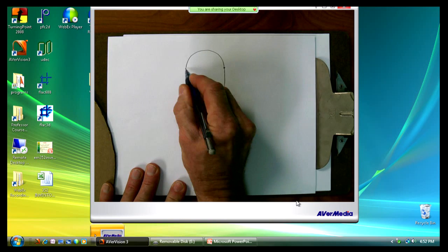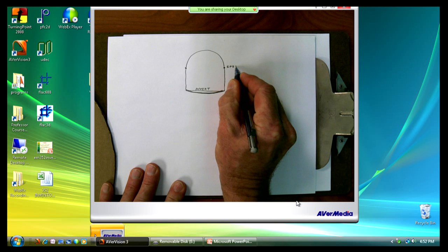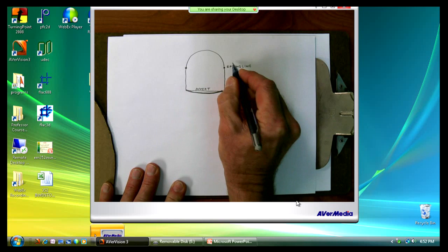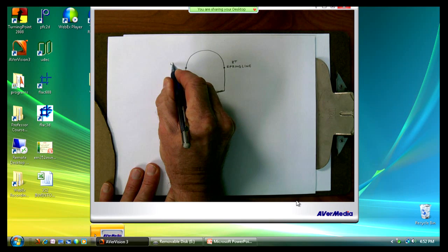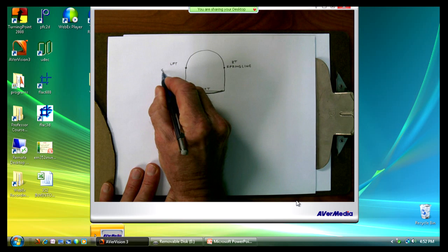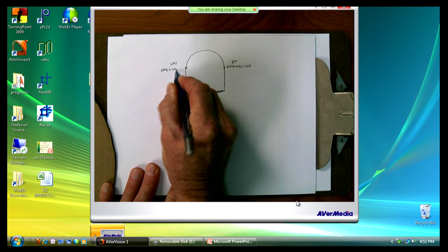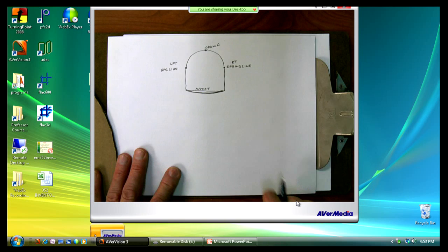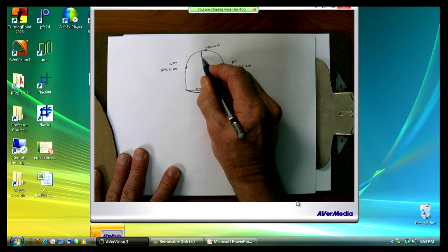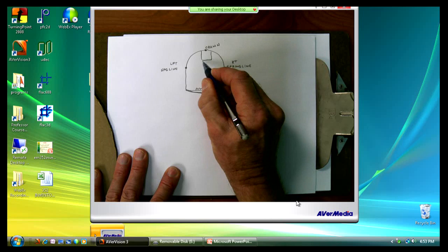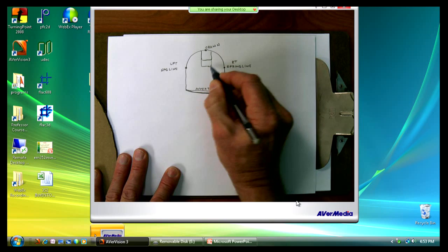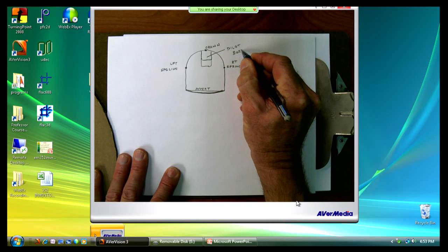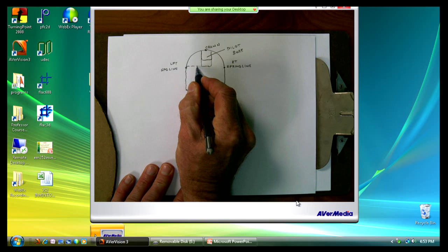Where it starts to turn is called the spring line. So that's the right spring line, the left spring line. And then this is called the crown. Now, it isn't uncommon at all for us to do a pilot tunnel, the pilot bore, up in this area. Sometimes they bring the pilot all the way down here, and we call that the pilot bore. And that lets us get in there and see what's going on. And then sometimes we excavate the shoulders after that.